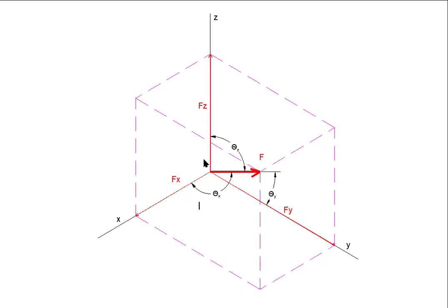Okay, here we're going to use the directional cosines to calculate the force resultants for any 3D force. All right. So remember that we break it down into a theta. So our theta x is from the actual force itself to the x component, and so on. So angle theta x, theta y, and theta z define that.